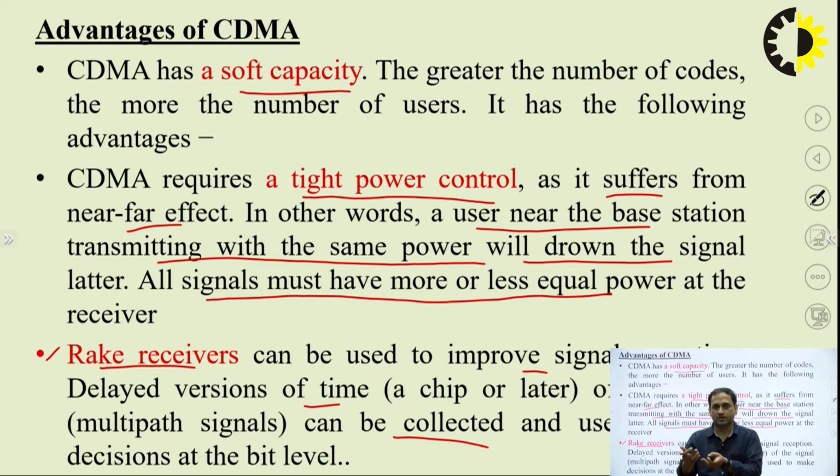If the received value is above the threshold, it represents logic 1. If the received signal value is lower than the threshold, logic 0 is observed at the receiver. For that purpose the rake receiver is there in the CDMA system, which contains correlators and integrators at the receiving side,